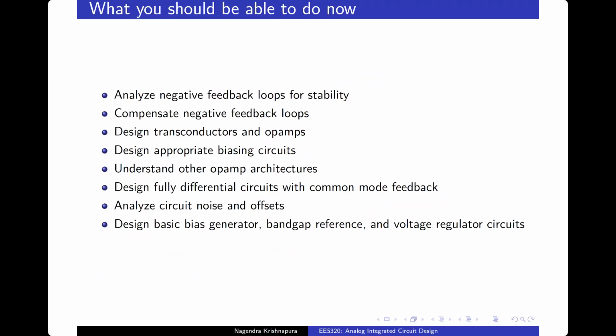Now, if it is one particular corner, like in the assignment, whether you have body effect or not is irrelevant. The only thing is you don't know what the value of threshold voltage is, but in the replica bias also, you can try to have the same body effect and then get that. But the main thing in design, when you come to designing real circuits, is to make it work for all the corners.